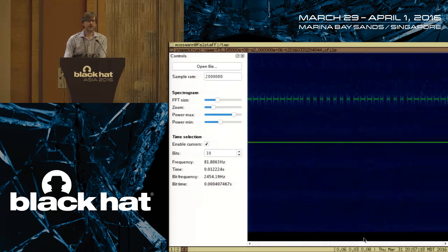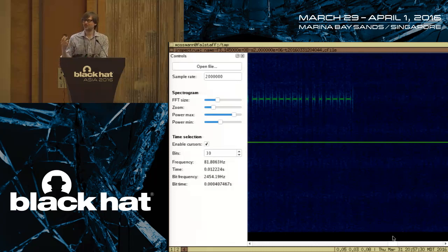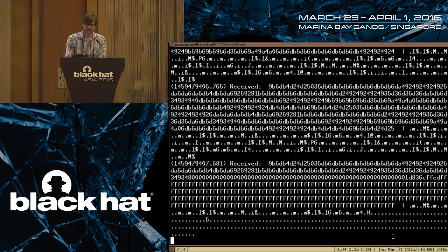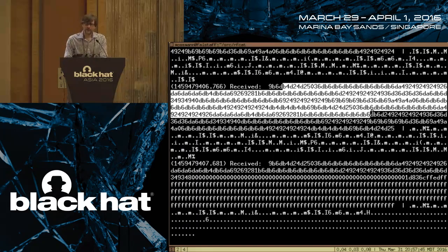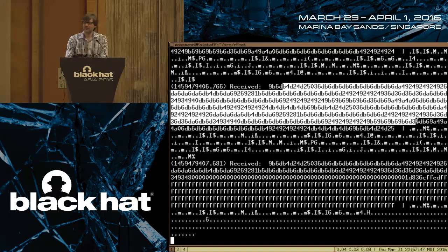If I were to compare this, I'd probably notice that it's really transmitting the same information over and over again. That's just a crude way of dealing with unreliable radio communications. They could use some sort of sophisticated forward error correction, but they don't. They just send the same packet a whole bunch of times in a row and hope for the best. That's a cheap and easy way to improve the reliability of a radio system. So it's not surprising that we see a lot of repetition here.